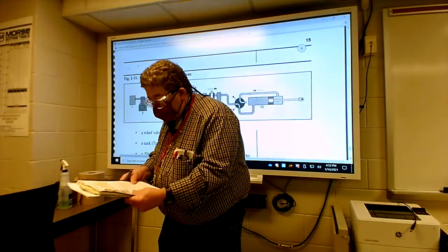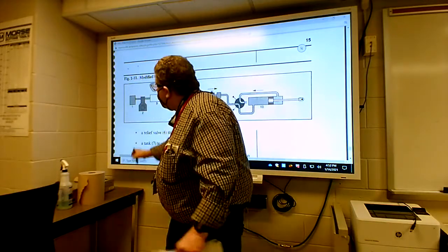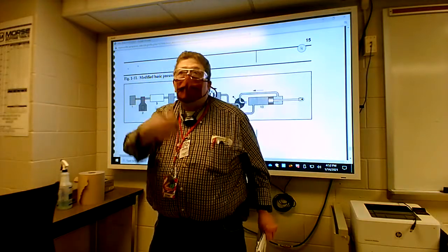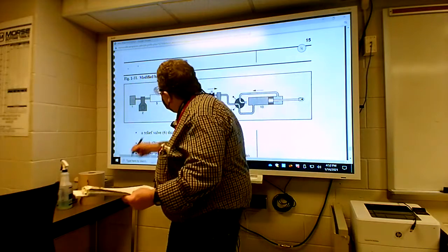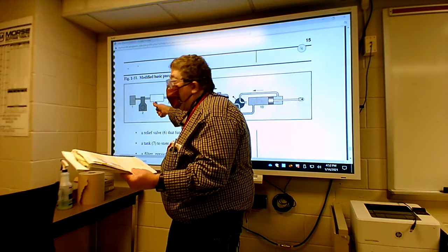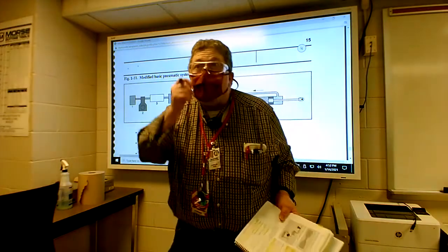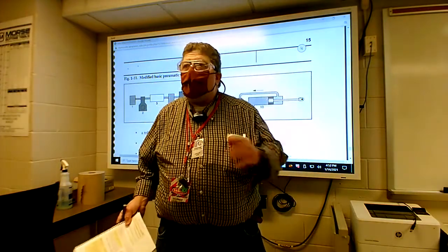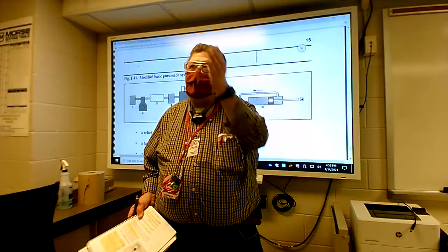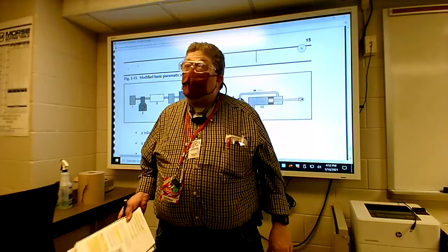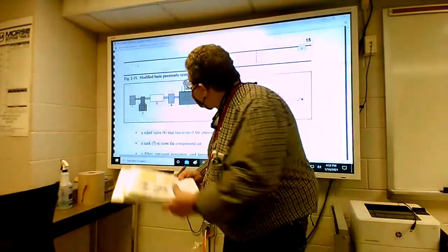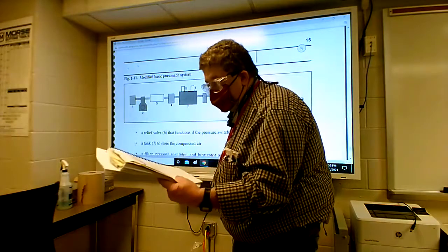So here you clean it before you get to what? What's number two? That's the compressor itself. That's going to take it and shove it into a smaller area, going to boost the pressure. Okay. What's number three? Yes. Now, what was I saying a while ago? An aftercooler. Anytime you go up to even a small compressor, you've got an intercooler between stages and an aftercooler because it's going to be hot. It can burn you. It's that hot. Okay. Number four.